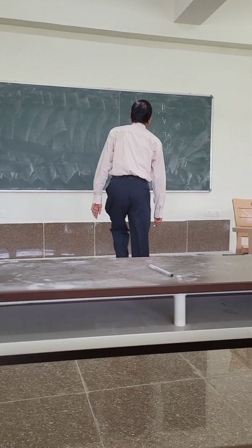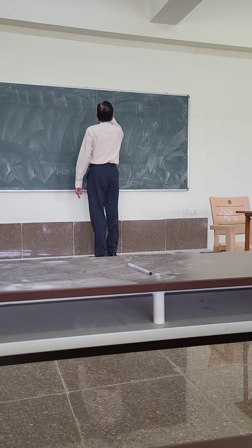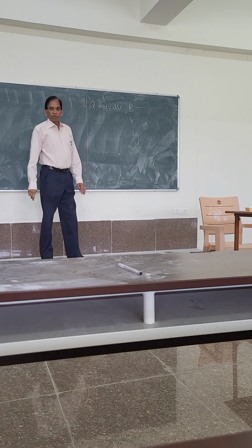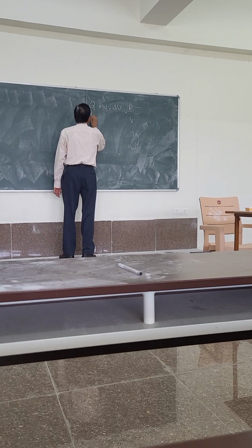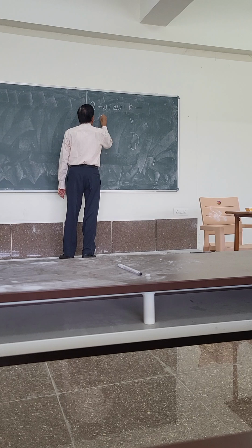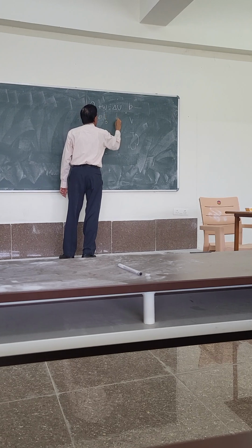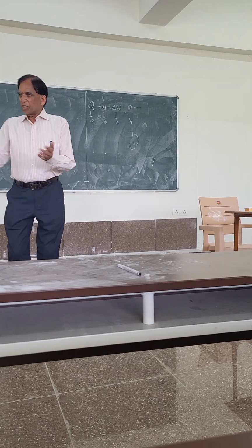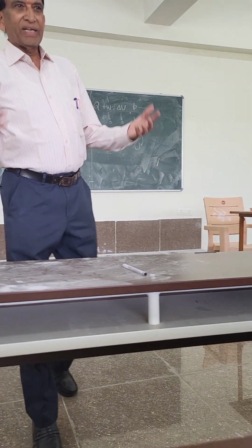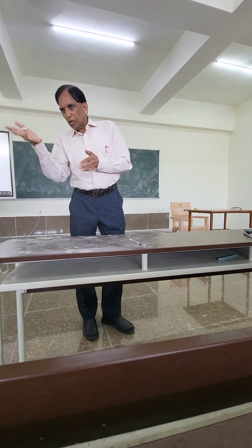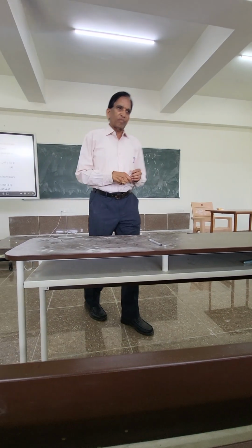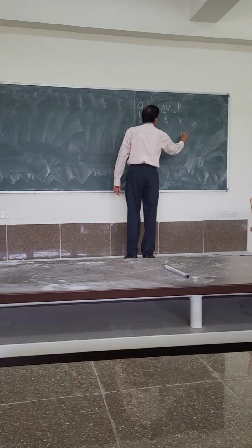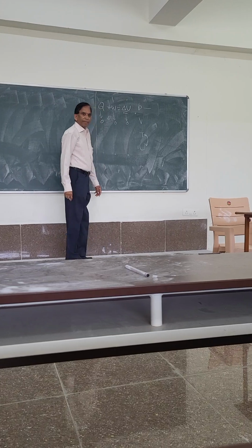Now what is the first law of thermodynamics? It says delta U is equal to Q plus W. So what we can do is make one of these terms zero. If you make one of them zero, it is easy to calculate the other terms, right? If I can construct a process where one of them is zero, it is easy to construct the process. We already said that delta U equal to 0 is nothing but an isothermal process.